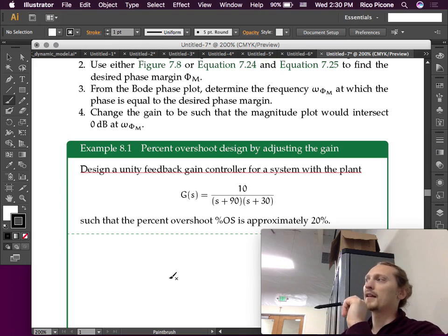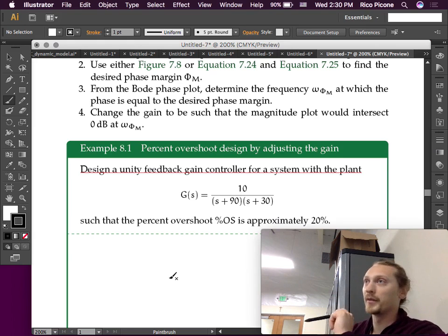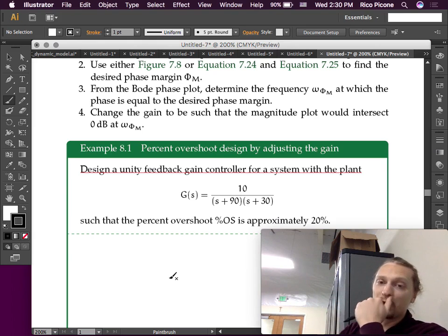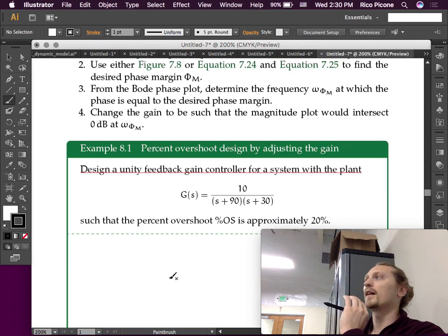If we had one pole in the right half plane in open loop, we would need at least one counterclockwise encirclement of -1, but we don't need that. So we know that the open loop is stable to start.